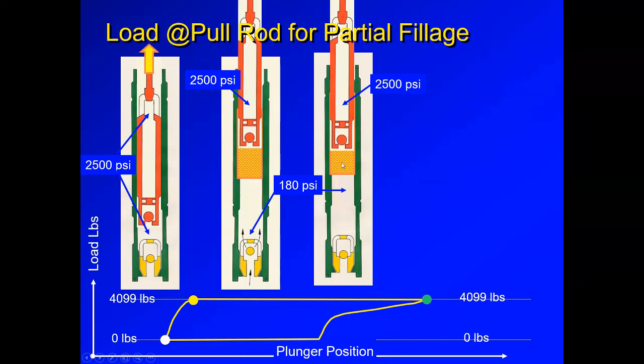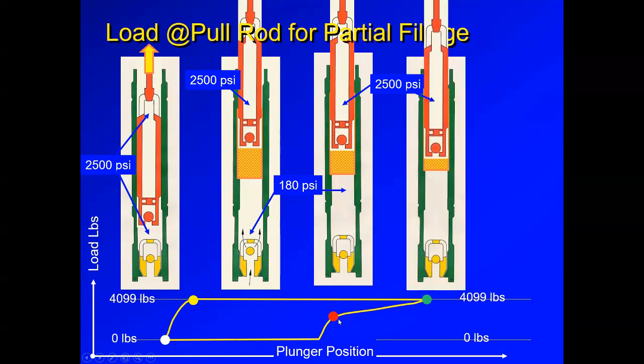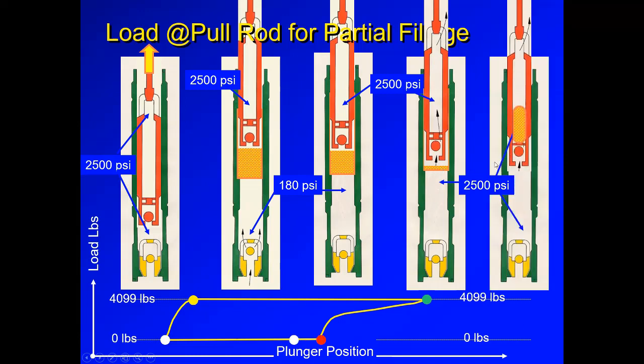Now the plunger will have to move to compress the gas up to a pressure that exceeds the 2500 psi. So it will be moving down, compressing until 2500 psi are reached, and the traveling valve opens. Once that opens, it should move all the way down. Of course, there will be some gas still in the chamber, so the gas passes first, and then some liquid will be pushed through the traveling valve into the tubing.